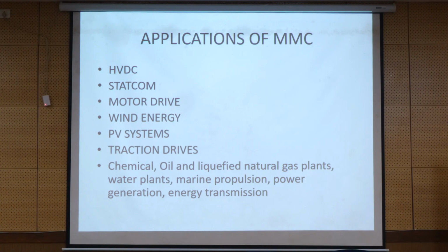Up to now we have come across the basic conventional multi-level inverter topologies. There are two ways to work in the case of multi-level inverter topologies. One is developing the structure, and the other is the modulation strategy. With the minimum number of switches, you can obtain more number of levels.